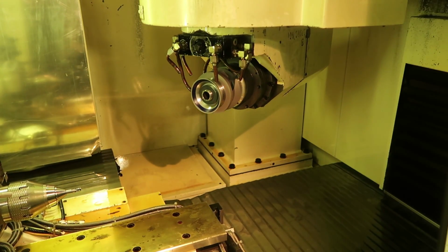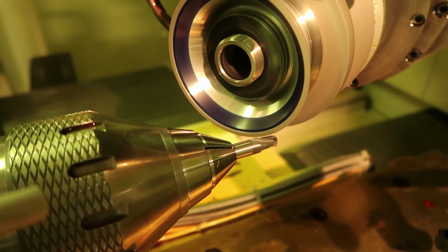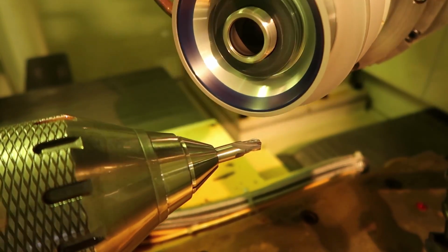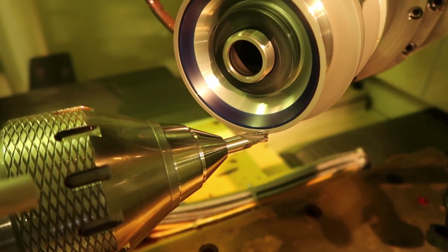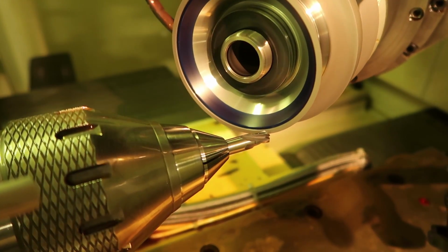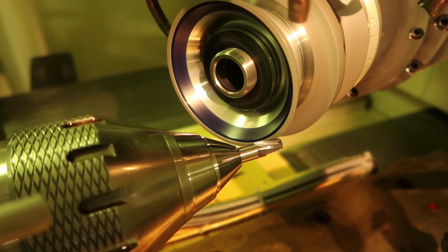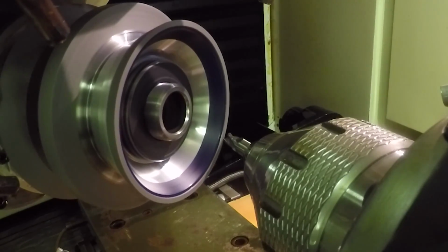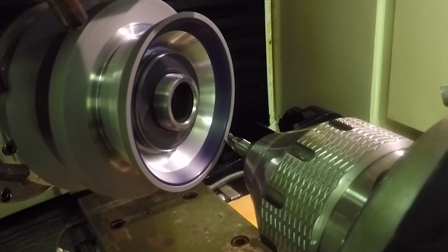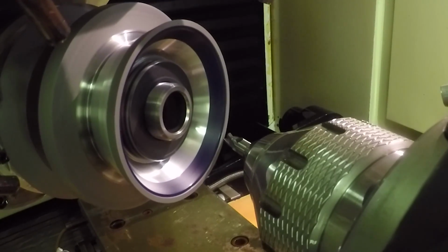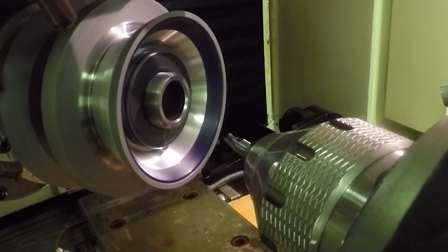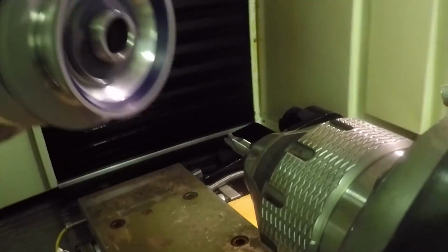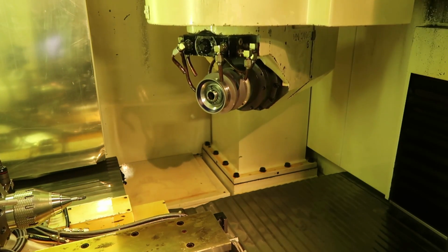Let me come back and grind the tip relief angles. These are full 5-axis moves here to grind this geometry. So that's the secondary clearance angles, the tip, and then this is the start of the primary, and here's the primary clearance angles on the tip. So that's it running dry with no oil on it, just so you could see it, because you wouldn't be able to see anything with the oil.